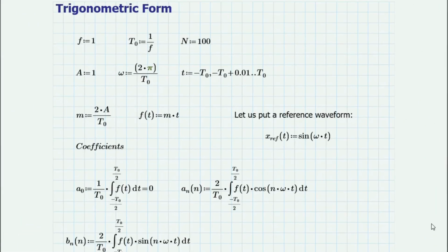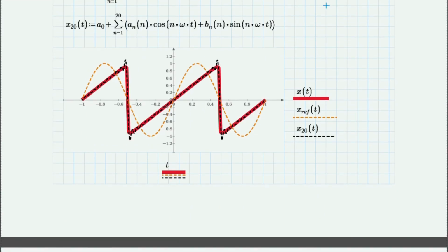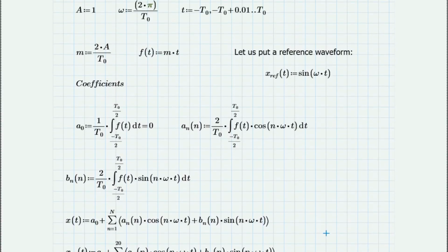We begin with the trigonometric form, where we mathematically decompose the sawtooth into its component sine waves. In the file, you'll see our base parameters defined with amplitude A and period T. Because our waveform is centered and has odd symmetry, the coefficients a_0 and a_n are 0, leaving us only with the sine coefficients, b_n.